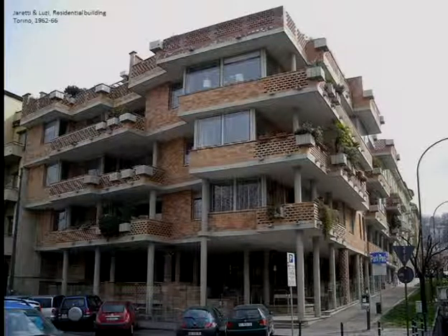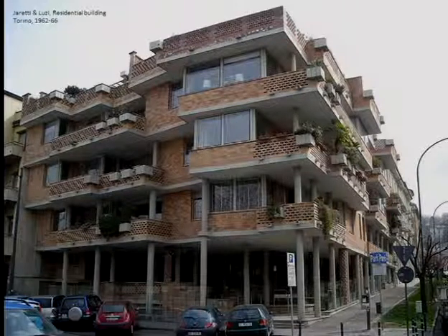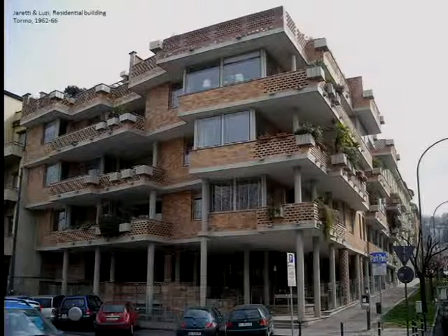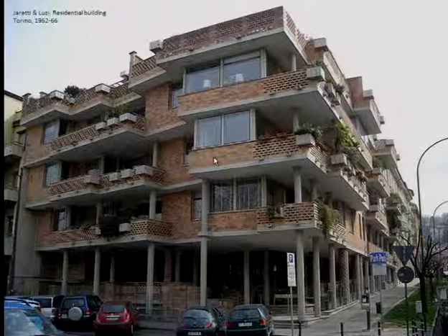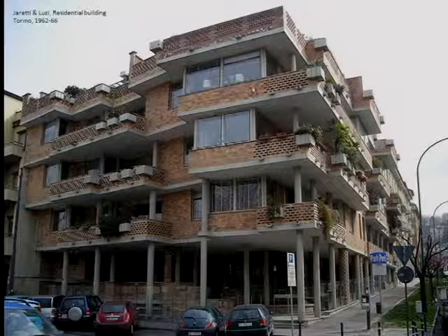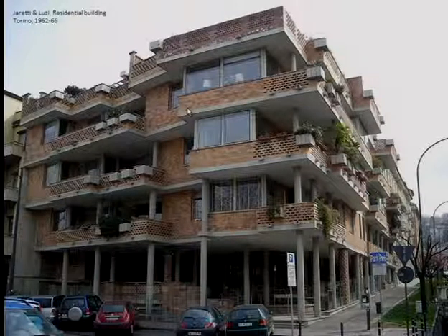So you don't care to make them nice and fancy. You just show the brutal part of that. So in order to save money, they weren't really rich, but they really wanted to make nice architecture. What they did is that they rotate the brick vertically so that you see this indentation on the facade. You see the frogs, but you save a lot of material because you put them vertically.